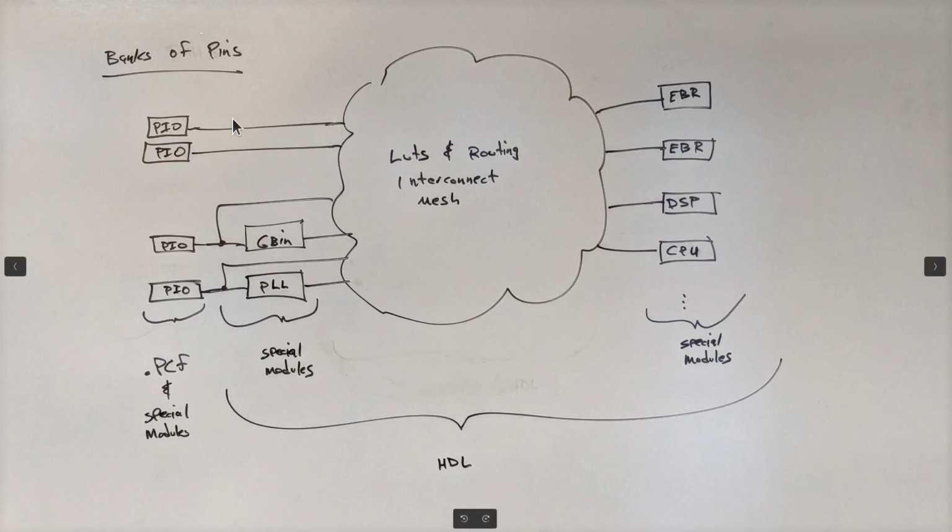which is what we're going to do on day one here, which is simply here's 1 or more input bits that go through basically a truth table lookup. That's what a LUT really is. It decides what to do with its logic, calculates. Maybe I'm going to take 2 binary inputs and say A ANDed with B and output the result of that over here, or something like that. That would be more sophisticated, but it's still a combinational circuit. It has no state. It has no concept of time. So let's start with combinational circuits, not sequential, and just look at how the compiler works and get used to what's going on, how to configure it, how to build our projects.